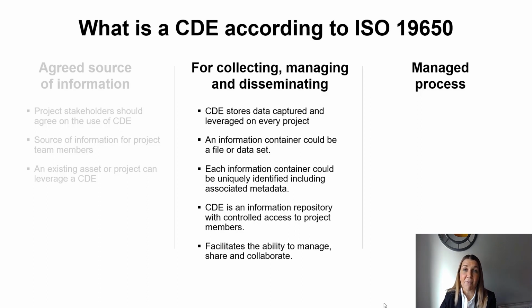A CDE is an information repository with controlled access for project members. Assigning the relevant permissions to project members to control and make accessing information concise and relevant to the task in hand and the latest version. But the CDE is not necessarily a single technology solution. This can be several connected solutions capturing additional metadata for a single project to form a CDE. It facilitates the ability to manage, share, and collaborate, providing the right information at the right time for each project member.